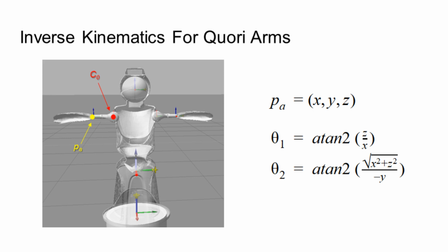Finally, we define the coordinate plane such that the x-axis points out to the front of the robot, the y-axis points out to the side of the robot from which the arm originates, and the z-axis is normal to the ground plane, assuming the torso is vertical. We chose to define the coordinate planes for the left and right arms as reflections of one another so that inputting the same command for both arms would lead to symmetrical movement.